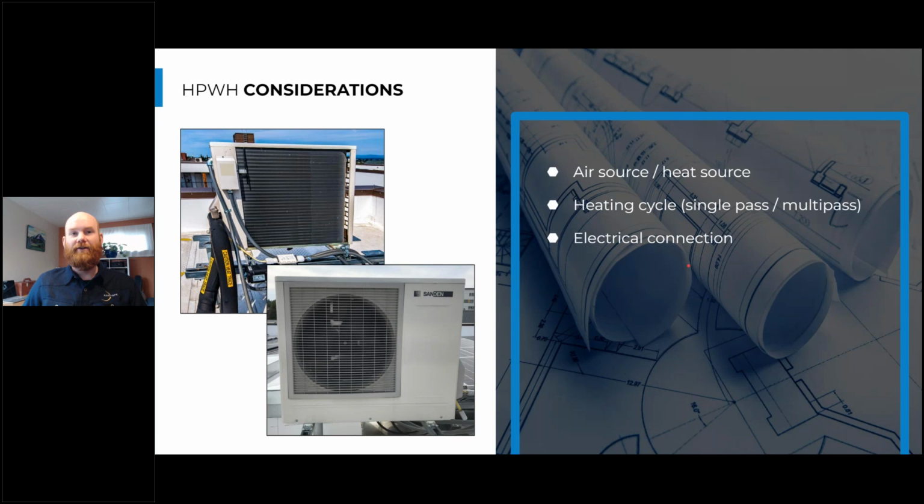And the other thing to consider is some heat pumps will be 3-phase at 208 voltage. Others will be 208 voltage at single phase, and so forth. So really understanding what the electrical requirements for that device are is a critical thing for us all in any system design.